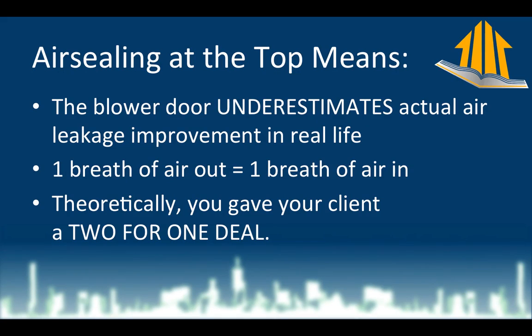So I mentioned a second ago that the blower door test is going to underestimate how good this is actually going to be. That's because when we depressurize a house, we blow air out through the blower door, we're getting 100% of the leakage in the house as infiltration. In real life, half of the leakage in a house, because of stack effect, and HVAC and wind, etc., is going to be exfiltration. Half of it's going to be exfiltration, and half of it will be infiltration. That means half is going out, half is coming in to replace what just went out.